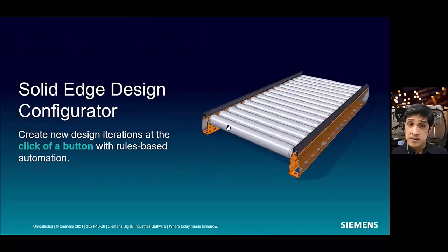Now here is a new enhancement which I'm really excited about. It's the new Solid Edge Design Configurator. This is a rule-based engineering configurator completely embedded within Solid Edge. What it does is that it enables the quick customization of products based on design parameters and rules, such as the weight or size of a package down a conveyor.